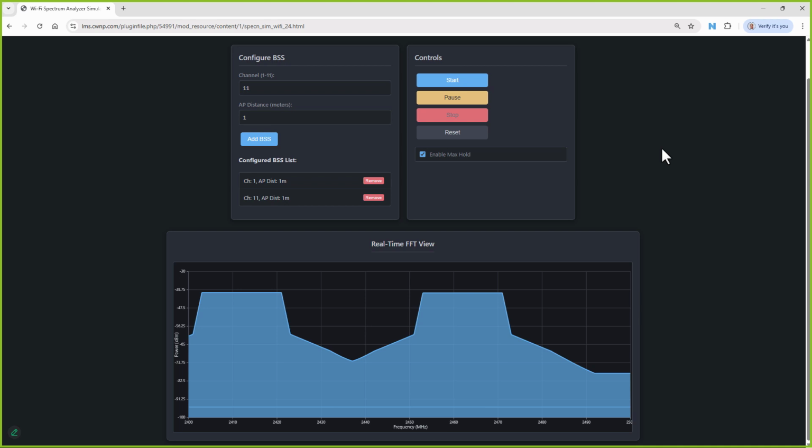And so if one of them's transmitting while the other one's trying to receive, the side bands from the transmitting radio are going to massively raise the noise floor of that radio that's trying to receive. And it's going to impact the performance and the ability to demodulate and then decode the data appropriately. So that's, for today and the future, that's really where this comes into play a lot, because we're going to see more and more multi-radio APs as we go forward.